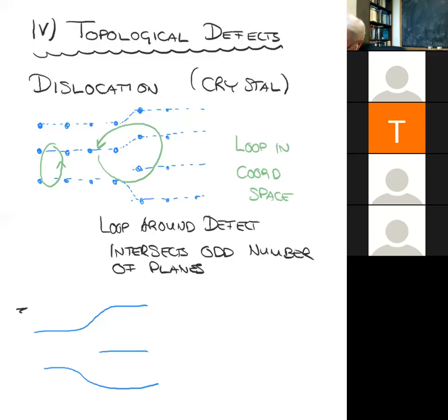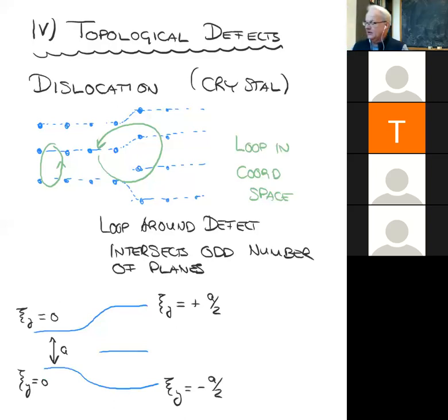So of course, the direction in which they're displaced is the y direction. You can view the crystal on the left as not being displaced at all. So these crystalline planes are exactly in the right spot. And if the crystalline spacing is a, then this plane here is displaced by plus a/2, and this plane down here is displaced by minus a/2. And we're a little unsure as to what to do about the plane in the middle, and you'll see in a second why that is.